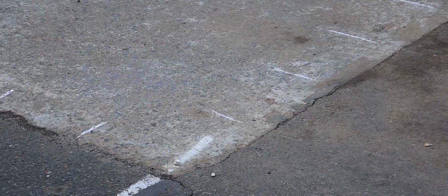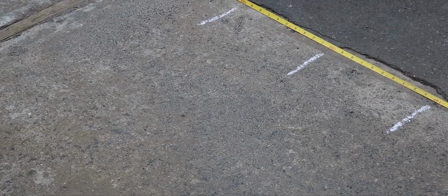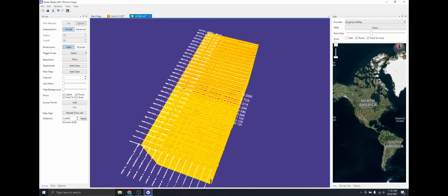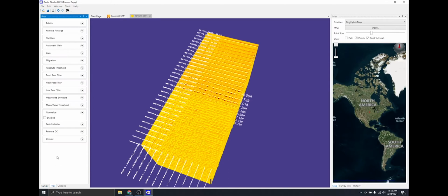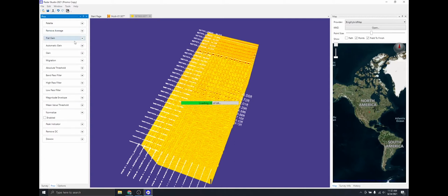Next, we will have to select the line separation. This will differ for each job, as the size of the target being scanned will not be the same. If you are not sure of the best distance for separation, use the width of the radar antenna, which can be entered into the software as 1.2 feet or 0.37 meters. The quality of the results from a 3D survey are dependent on the number of lines acquired, the separation of these lines, the closer the better, the accuracy of the grid layout, and of course soil conditions.